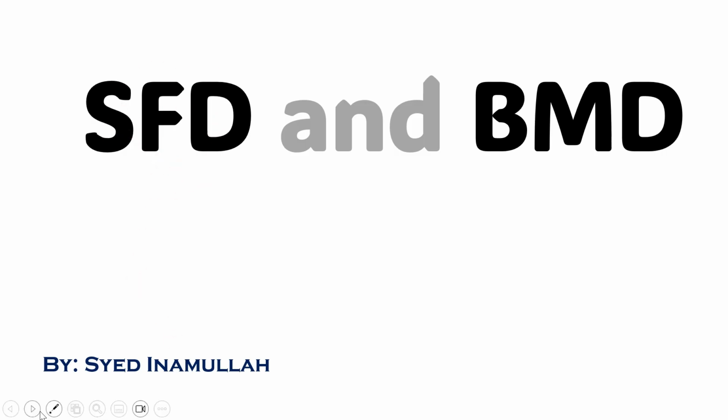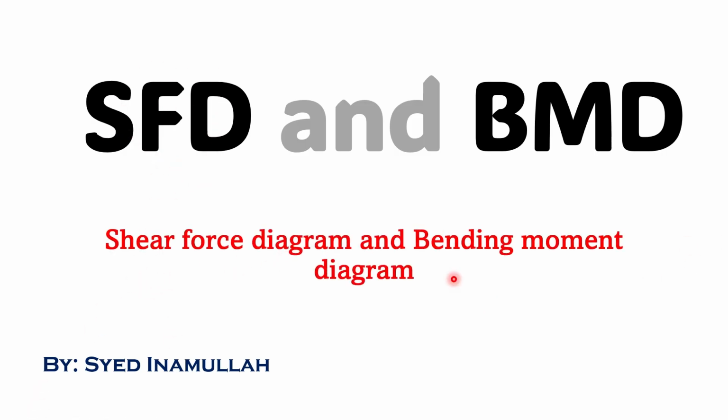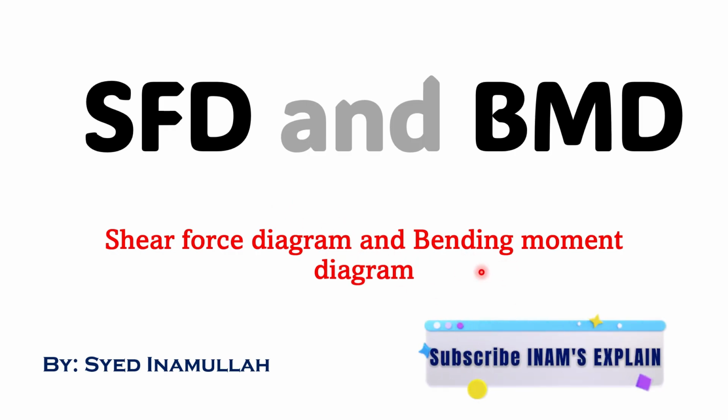And what is the relationship between the shear force and bending moment? The shear force at a section can be thought of as the rate of change of the bending moment. When the bending moment changes, the shear force also changes. These both are interconnected. In the beam, maximum bending moment occurs where the shear force changes sign from positive to negative or vice versa. Meaning the maximum bending occurs at a point where the shear force value is minimum or zero.